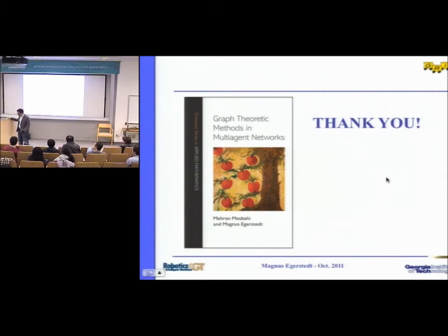Right. The one aspect that's cheating about the grits thing is that if everyone has decided where they're supposed to be in the EPFL logo, and you can somehow measure where you are relative to where you're supposed to be, then you can do it. Or if you want to solve this who-goes-where problem in a centralized way, the who goes where is the assignment problem, and there are cubic time algorithms for figuring out who should go where. You basically sum up the squares of the distances, and you can solve it. But if you truly have 278 robots, there's no way you can do this. And in my case, I had 15 robots.